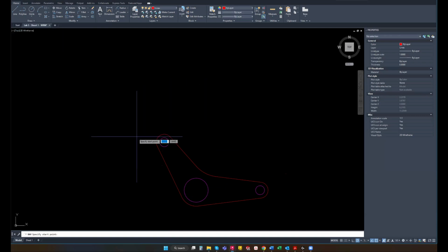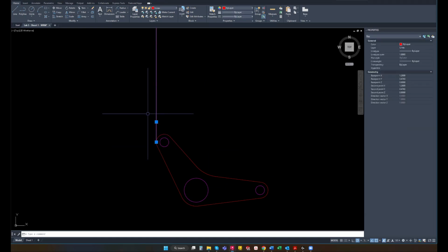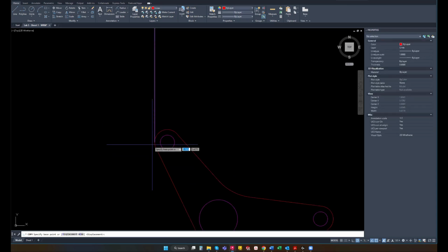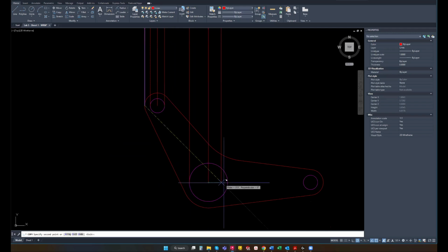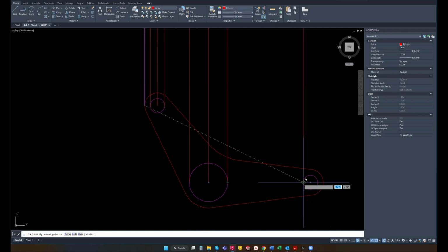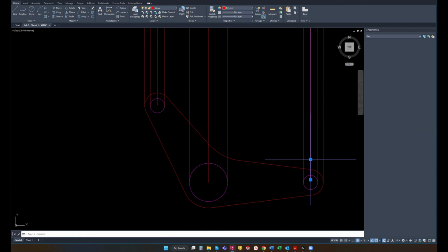But I'm going to do RAY enter and then project straight up wherever I have what I call important lines, anything that would show in the top view. So we're going to grab the edges of our circle, the quadrants of our holes, our center points of our holes, and the edges of our heart.